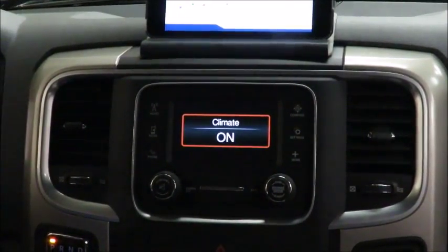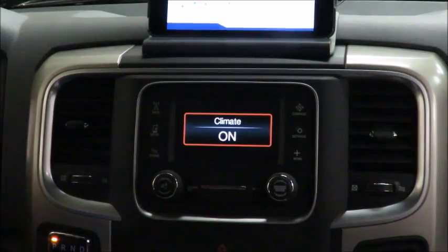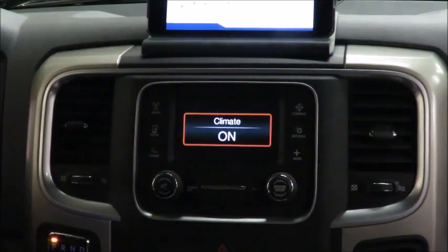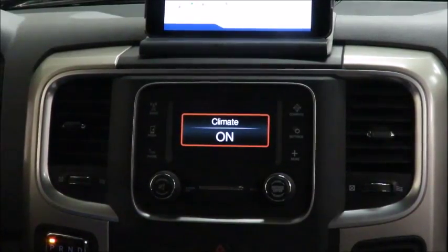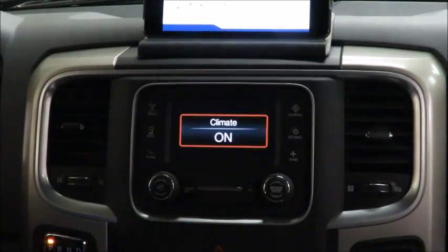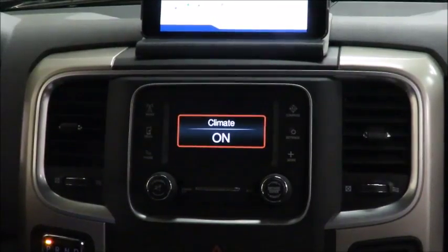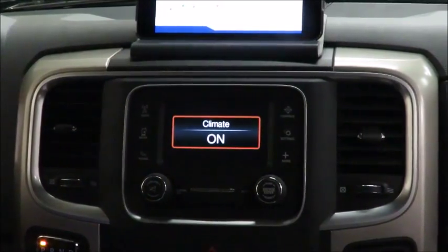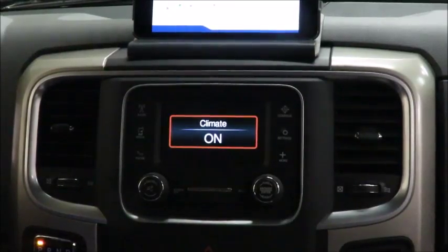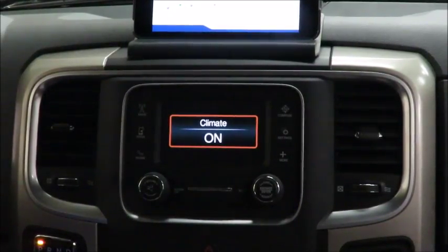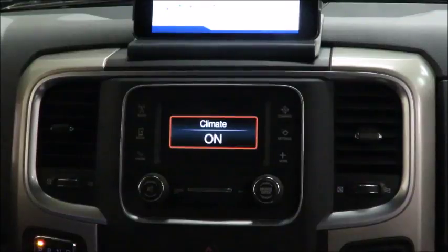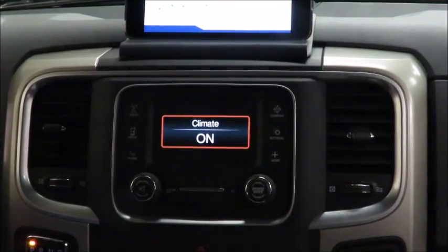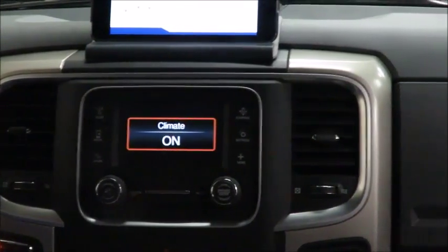Examples of common post actions could include clearing of specific update diagnostic trouble codes, calibration learn procedures, or reinstalling user-specific settings, for example, radio presets. As a final step, the OTA cloud will again perform a complete synchronization or inventory of the vehicle to identify that the update procedure has completed successfully. A final transactional log is then compiled and registered with the OTA cloud for archival and future data analysis. This concludes our OTA update.